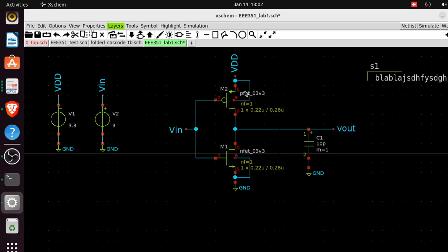So either would work, but what we'll be working with is varying the width, not the length, because many times the length specifies the process node. So if it's 180 nanometer, most likely you want the length to be the same for all the transistors, all the devices there, for one reason or the other. So at best, you want to just vary the width. That's what we're going to be doing. They would have the same length, but we'll give them different widths.